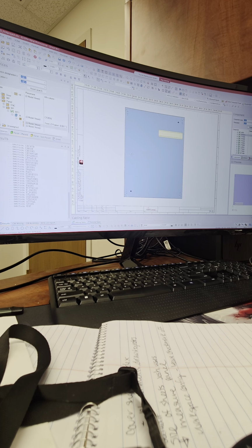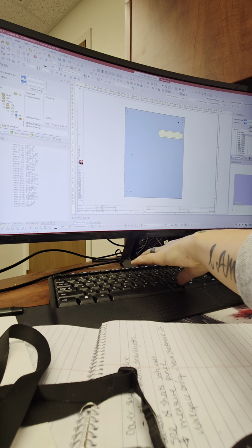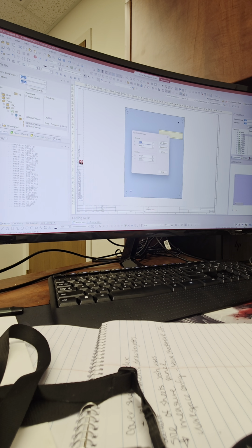Okay, so when you say, okay, this is where it quote unquote should go, don't click to place. Instead, press P on your keyboard. That's for positioning. Okay, so now you have this reference on this little prompt where you have absolute positioning and you have relative positioning. So absolute positioning, for example, right now you have 10 inches from your left, 9.625, which was our approximate placement. So you can adjust this to be your 10 inches.